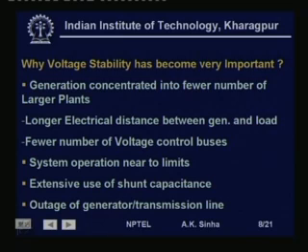Outage of heavily loaded transmission lines also creates the same problem, because if the line is heavily loaded, then the voltage drop because of the heavy current flowing through the line is going to reduce the receiving end voltage further, and again this can lead to a runaway situation.